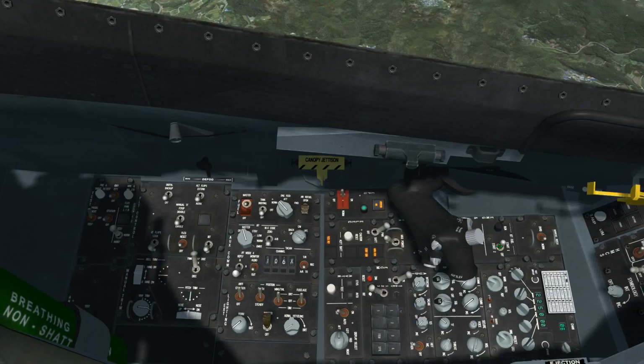Normally, the B system pressure will recharge those two accumulators in about 40 seconds, but because we're on EPU power and we've lost the B hydraulic system, we have no way to recharge the accumulators. So there's no way that you're going to be able to get this engine started. You might as well punch out now. So that all occurred because you didn't wait until you were below 20,000 feet and you used the JFS system.